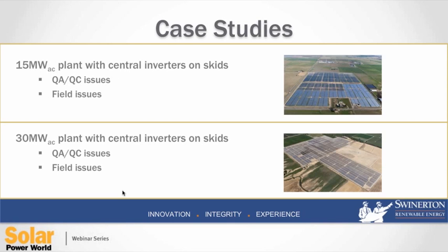We've now grown in just the last 18 months into a full grid operator. That's really what we're trying to build here. Our 30 megawatt site varied. It's for the same utility, but seeing the change in the utility, going to a DC monitoring solution, they want as much data as they can. That particular site was a single-axis tracker site, where now we have utilities asking us to also receive tracker points that are available, position, angle, alarms from trackers, because they use that to also help with their forecasting, their grid operation, and then in that case, really building a robust SCADA system where the utility has control.